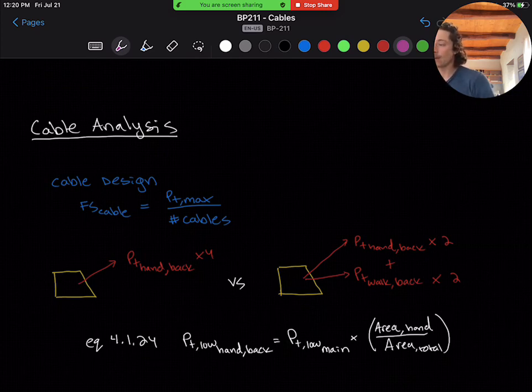cables. For our anchor analysis, it is conservative to assume there is friction over the backstay, but as little as possible, so that the majority of the force is transferred into the anchor. For our tower, tier, and foundation analyses, it is most conservative to assume significant friction over the backstay, so that a larger portion of the force is transferred into our tower, tier, and foundation components.